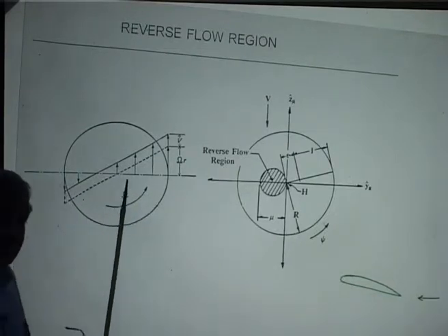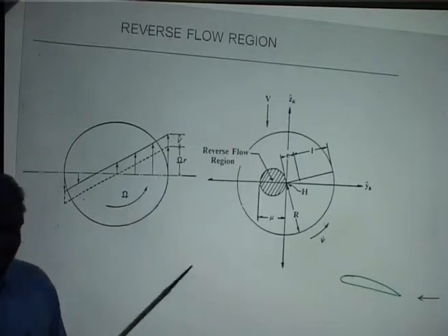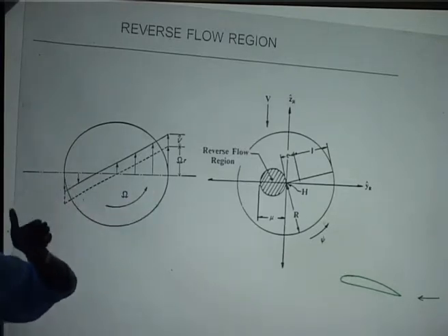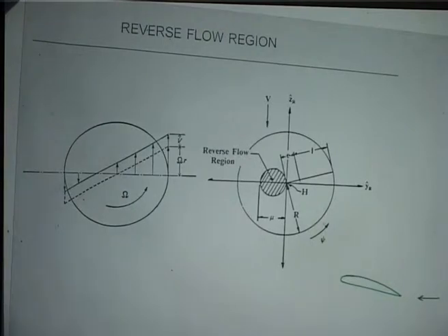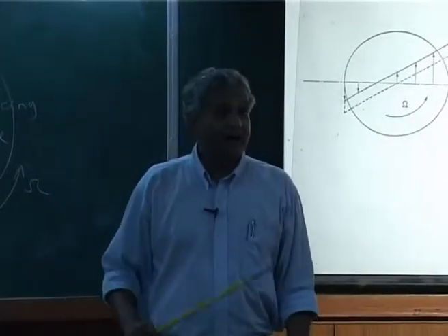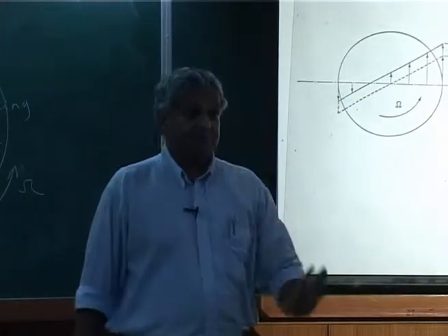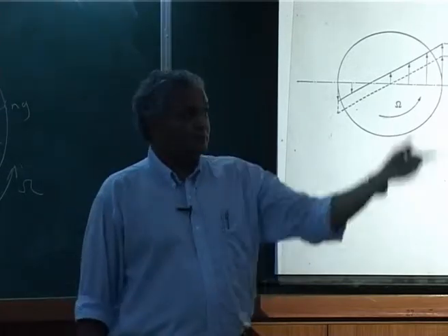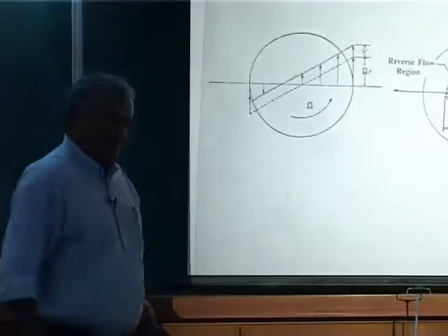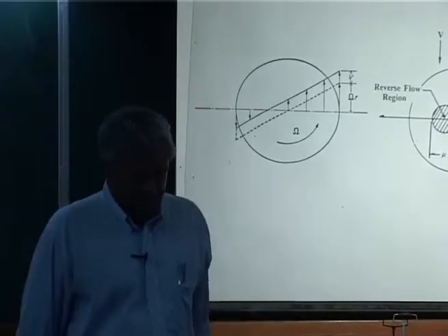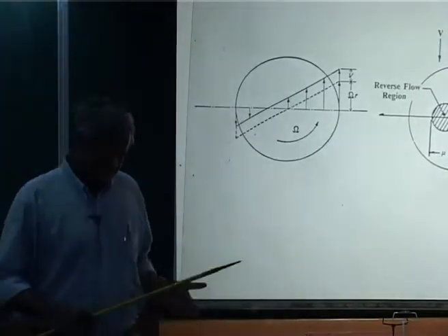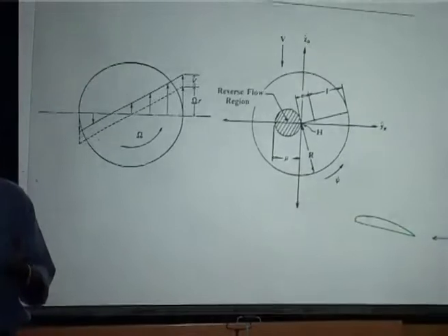Now, that is why in aerofoils for helicopters, when they get the CL, CD, CM, actually they go through a full loop. They will plot that CL versus alpha, alpha going to 360 degrees. That means you do one full loop, that means flow can come in any direction. Of course, earlier you can neglect it, in the sense, because there is a hub, you have to know what is the size of the region. These things we will learn later.